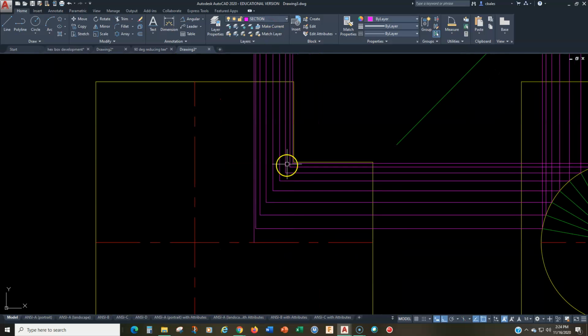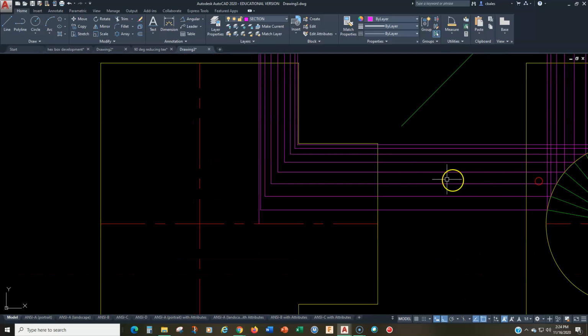Okay, so you see what we've gotten now. We've projected all these points across, and we have the stair step, staircase kind of look. That is our line of intersection, or more precisely, that is half of our line of intersection. So now we need to figure out how we're going to draw that kind of a curve, because we can't use a circle, we can't use an ellipse.